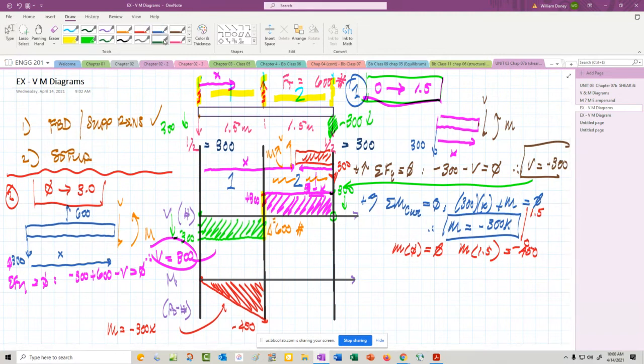All right, moving on, and we go to the bending moments. The moments about the cut, again, that's important. Counterclockwise positive on this section. It's about the cut. We're going to have 300x minus 600 times, now, again, we're using the distance from the 600 to the cut.